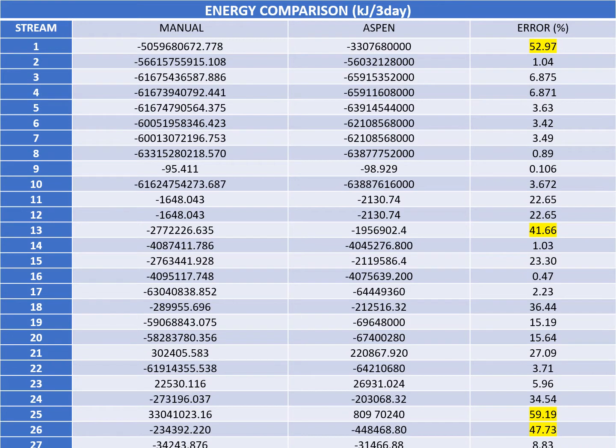Unlike mass balance, errors are much more significant during the energy balance computations due to discrepancies in steady states between manual and simulated values, and some components are not viable in the Aspen Plus, such as yeast and nitrogenous compound in the related streams, which cannot be run in Aspen, and other incorrect thermodynamic assumptions.